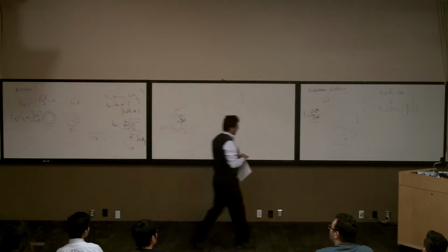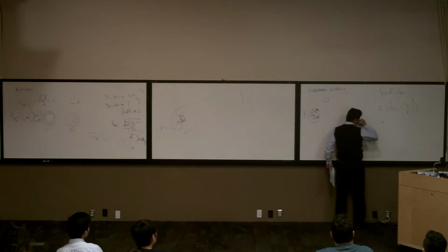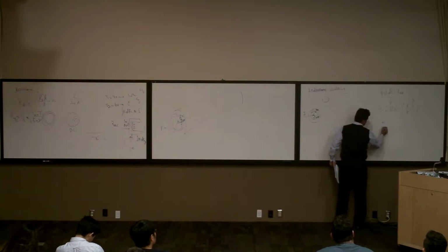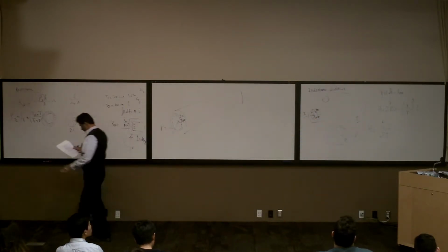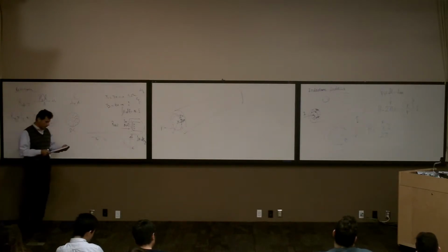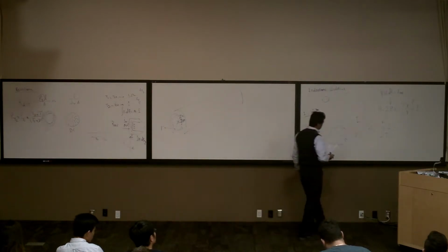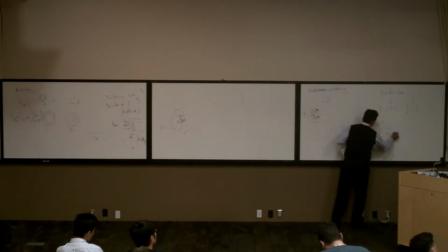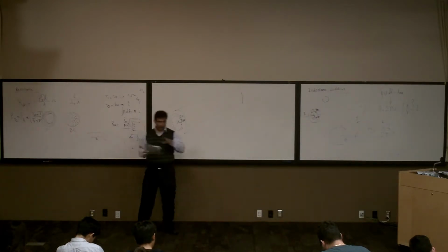So basically H is going to be x I over 2 pi r squared. This is the H inside the conductor. Should r be squared? Yes, you're right, this one should be squared: 2 pi r squared. And the unit is ampere per meter.